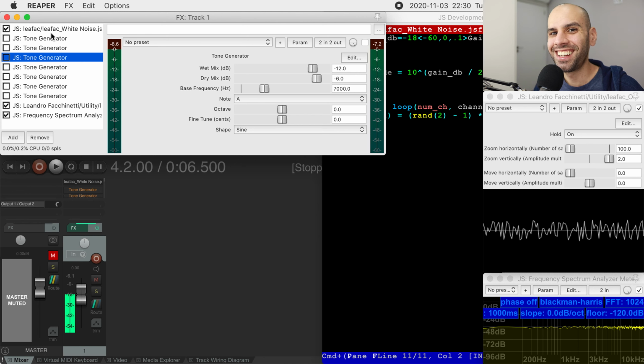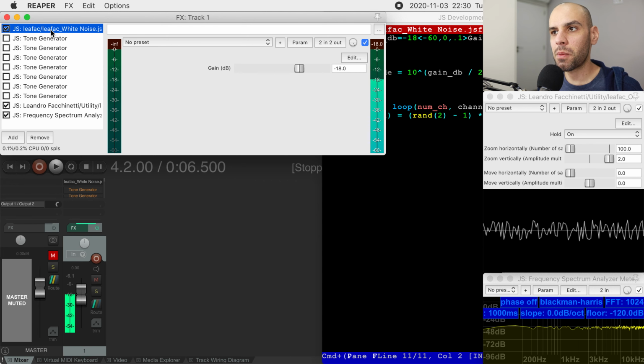Now you know. In case you didn't before, and that's a common thing for people to say, right? If you have a simple example that you want to write, you just generate white noise by picking random values, but very rarely people explain why that works. And that's why. Because you're generating these small snippets of waves in all different frequencies that are in all these different increments. And the effect that has, if you add everything up together, is that you end up with energy across the spectrum. That's how white noise generation works.